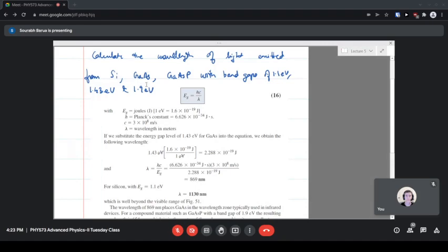So that's why this is known as a 3,5 semiconductor. Aluminum and gallium are in group 3, so they are called 3,5 semiconductors. You will come across that nomenclature sometime. They are called 3,5 semiconductors because one element is from the third periodic group and one element is from the fifth group of the periodic table. And here you can see phosphorus is substituting in place of arsenic, and so you have a ternary semiconductor here.